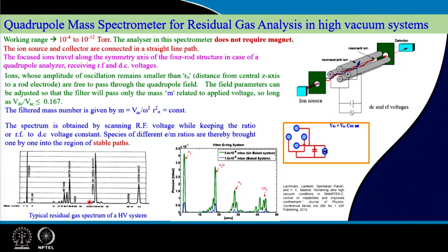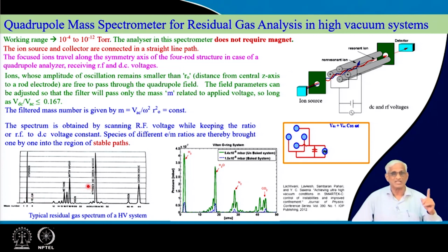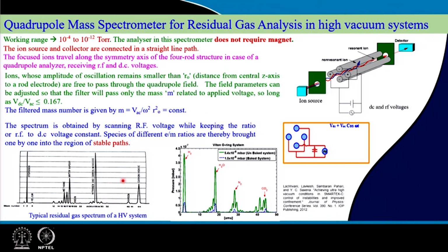Now, coming to the picture here, there is a typical residual gas spectrum. When you are coating a semiconductor, under these conditions you can tell what you have coated. Tomorrow, if the reliability of the device is not coming, then you would not know how to interpret. It is like the black box of an aeroplane when an accident takes place. From the RGA you can understand, oh, that day the peaks of silane were not much, hydrocarbons are there and interfering, p type is more, n type is more. That way RGA will be very useful for you.